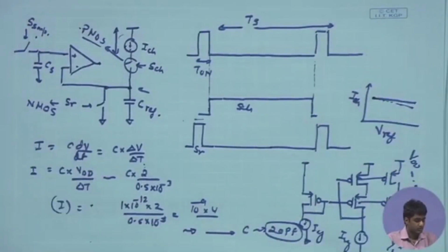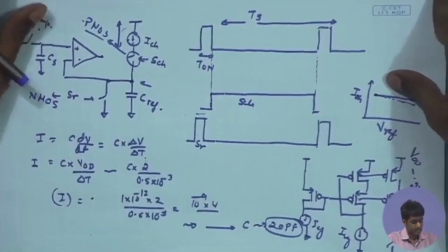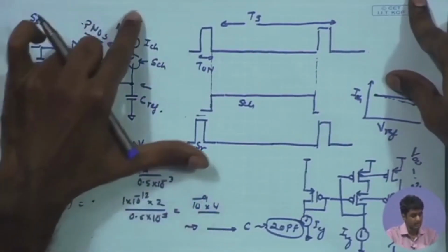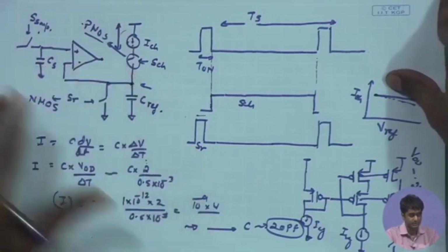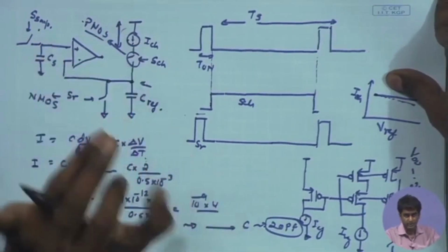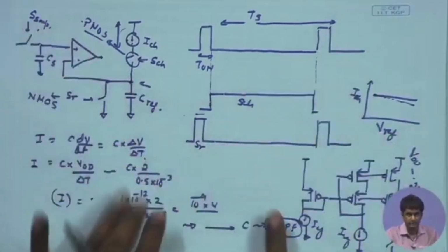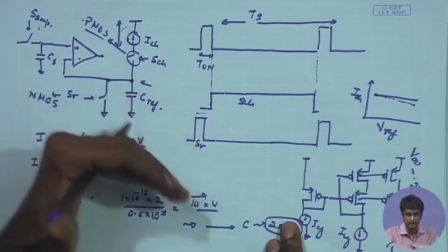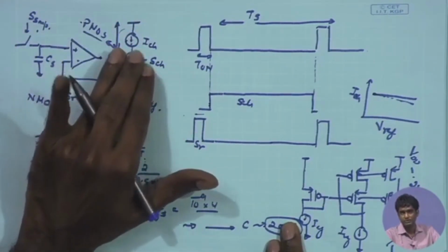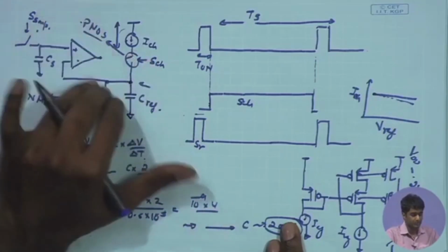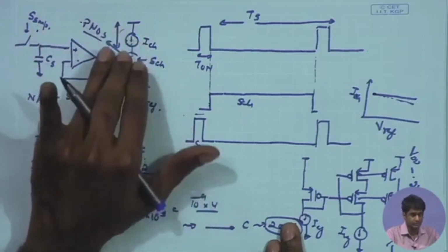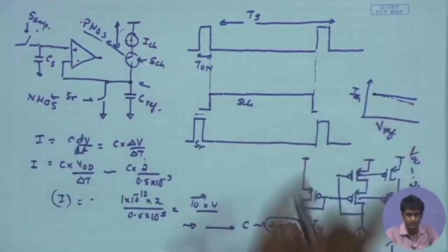So now we have discussed the second critical module for the overall design, which is our ramp circuit for charging the capacitor. We looked into the design or choice of the C-ref and the I charge. We looked at the trade-off that, despite the numerical value giving us a very small I, we should not go for that and rather choose a sufficiently large I charge so that it is robust enough and more tolerant towards process and temperature variations. And also we looked into the considerations for the I charge in order to make it sufficiently constant and to ensure that the slope remains relatively flat.